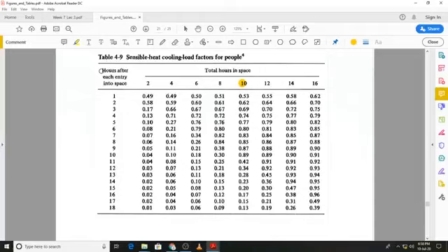And this is where you have to be careful how to interpret this statement. We are told to find out the cooling load at 1400 hours, and the people enter the conditioned space at 0800 hours. So what we want to see is that at the time that you need to calculate the cooling load, how much time the people have already spent in the conditioned space.